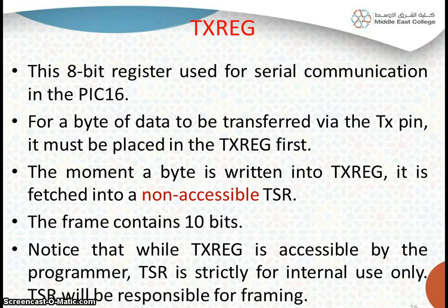This register TSR will convert the data which we have placed into 10-bit data. So it will be performing the framing action: it will add the start bit and the stop bit. We have to notice that the TXREG is accessible for the programmer, but TSR is non-accessible. It is only for internal use.